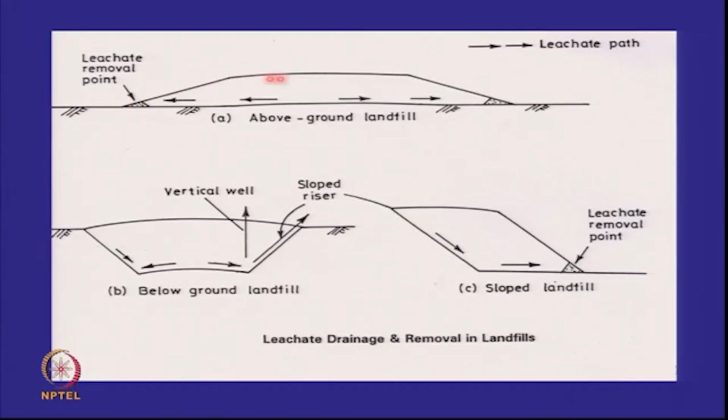I have an above ground landfill. If I don't do the proper grading at the base, suppose the above ground landfill has a base like this going down and coming up. All the leachate will come to the center and you'll have to pump it out. It can't come up by its own because this is low lying.